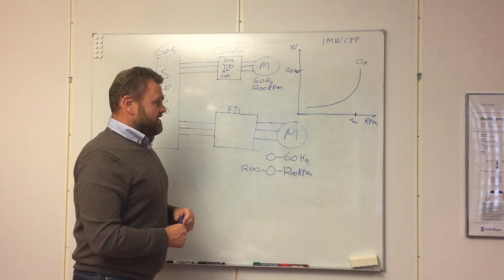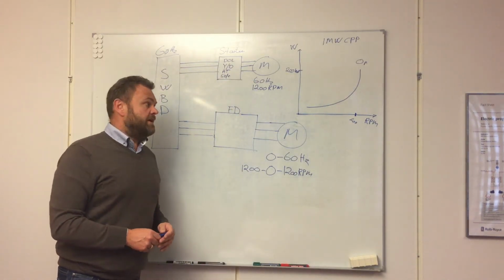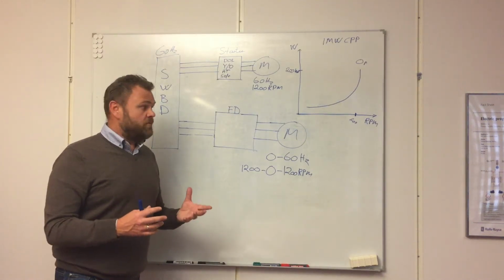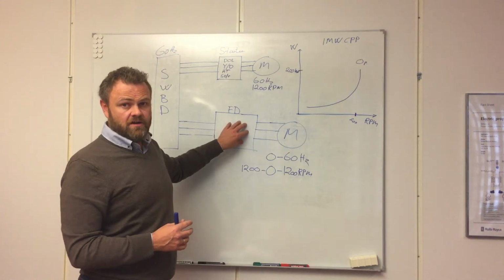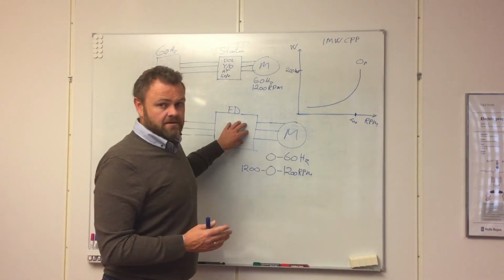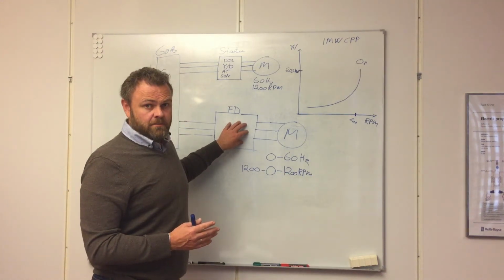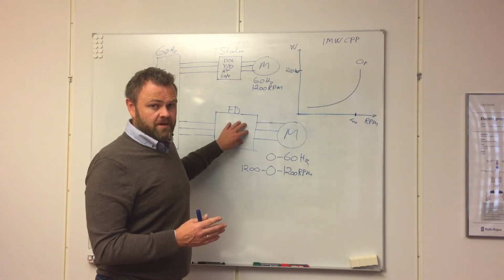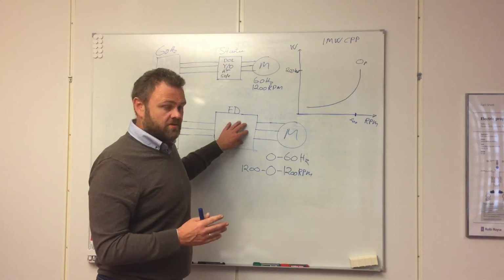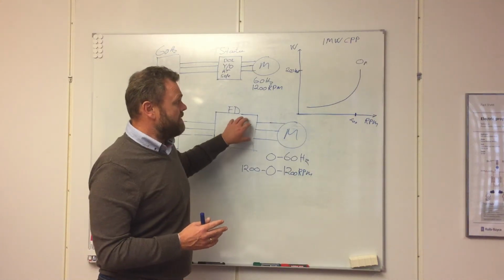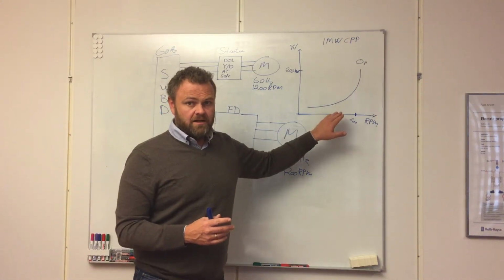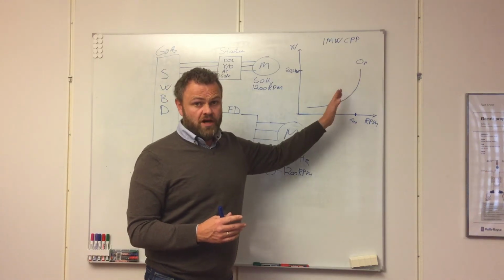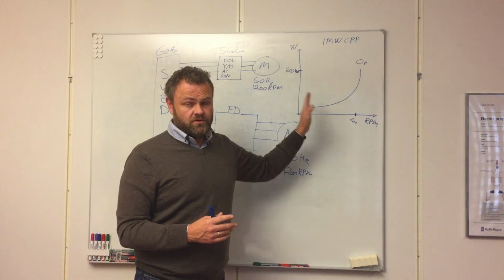And this is basically the only reason why we would like to have a frequency drive on a propeller. Because we want to regulate the RPM. That is the reason. We want to regulate the RPM on the propeller. And why do we want to do that? It is to reduce the losses on the propeller side.